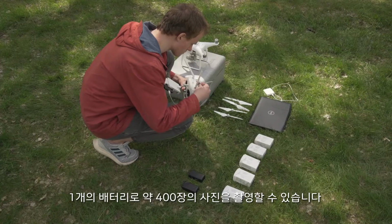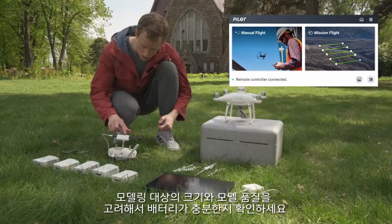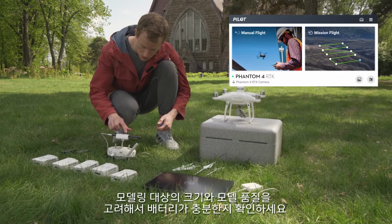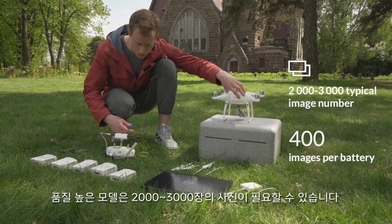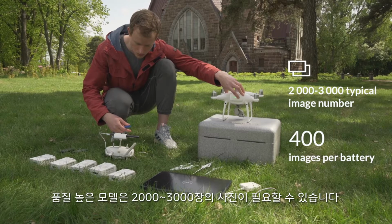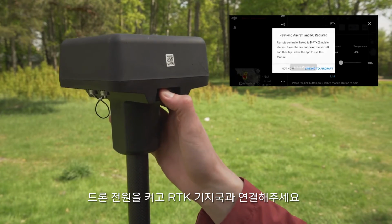One battery provides for capturing approximately 400 photos. Make sure you have enough batteries according to the size of your object and target level of detail. 2000 to 3000 images is a typical number for a detailed dataset. Power up the drone and establish connection with the RTK base station.